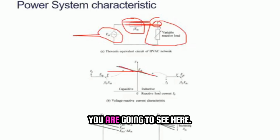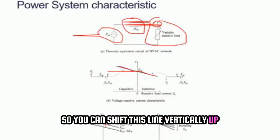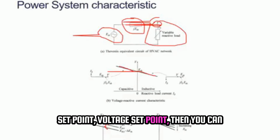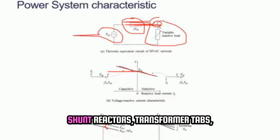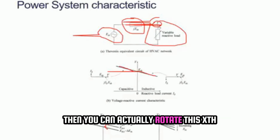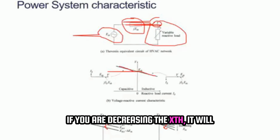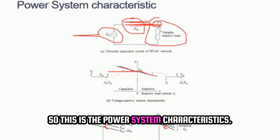So this is the slope which you are going to see here. Now let's say you want to improve the voltage, so you can shift this line vertically up and down by changing the ETH. If you change the ETH, or change the generator terminal voltage set point, then you can vertically move this line up and down. And if you change the series reactors, shunt reactors, transformer taps, which are the network parameters, then you can rotate this XTH in different directions. If you are increasing XTH, it will rotate clockwise. If you are decreasing the XTH, it will rotate in the anti-clockwise direction. So this is the power system characteristic.